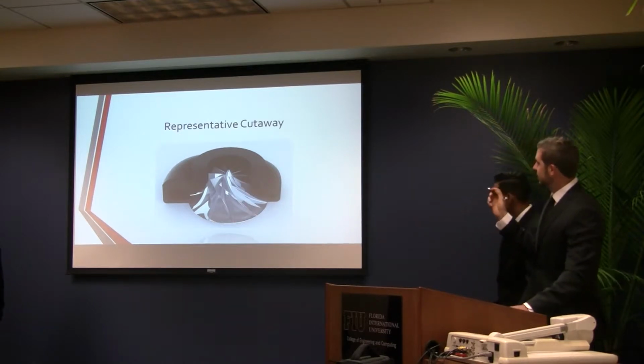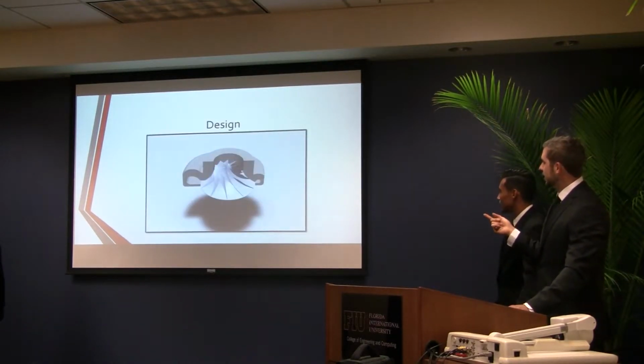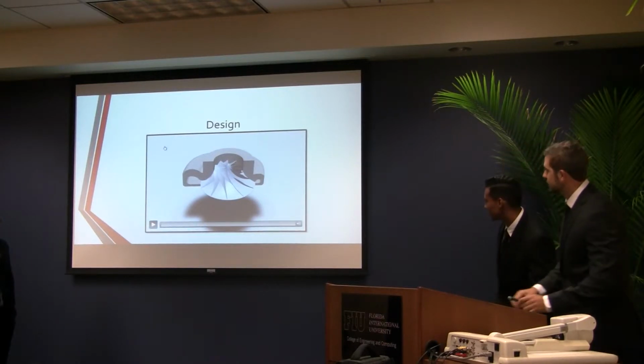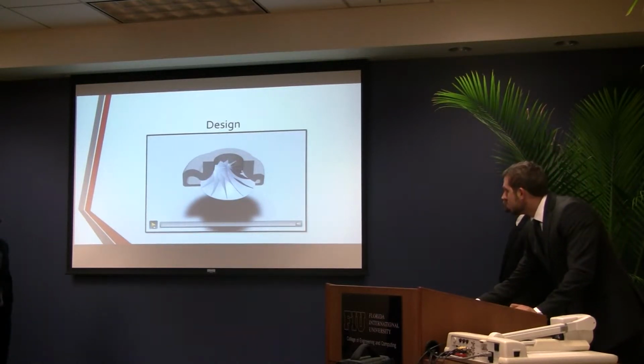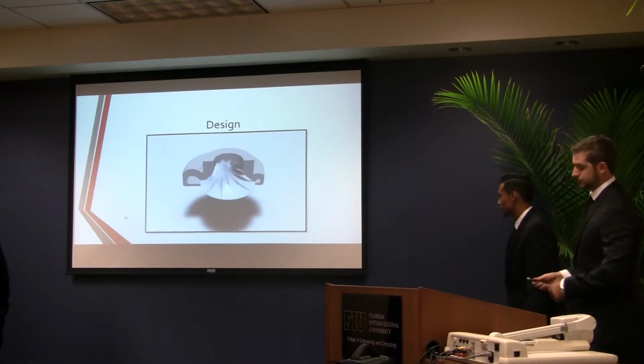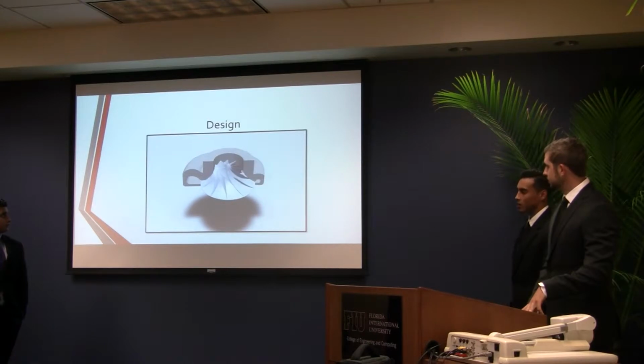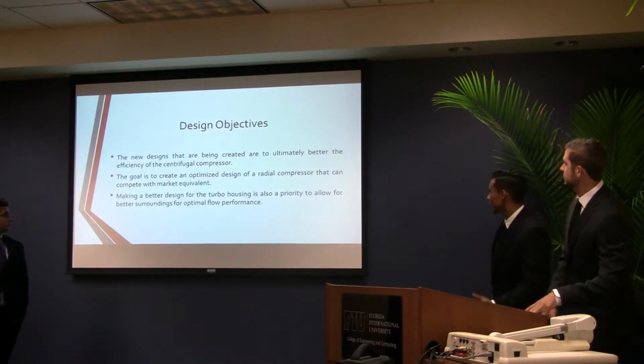Here is represented the cutaway of the whole system. We have the blades and the housing, and here you have video of the design. As you can see, it moves. We have forward facing blades, so it causes a higher pressure difference.